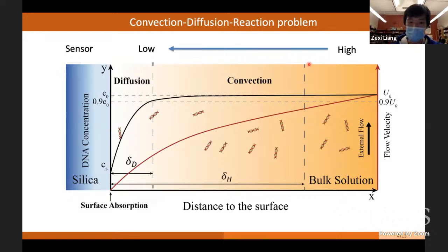That's why we involve micromotors. So in addition to the concentration profile, we first talk about the flow velocity. Assuming your motor is moving in the solution, you can change the coordinate system and look at the micromotor only. Assuming the micromotor is still and the external flow is passing around it, you have an external flow rate pretty high, U naught, far away from the micromotor surface. The flow rate will gradually reduce to 0 at the solid liquid interface, constrained by the no slip boundary condition in most of the solid liquid interface.